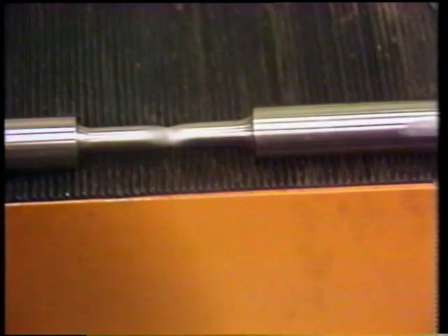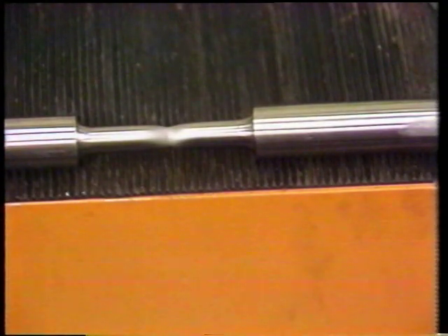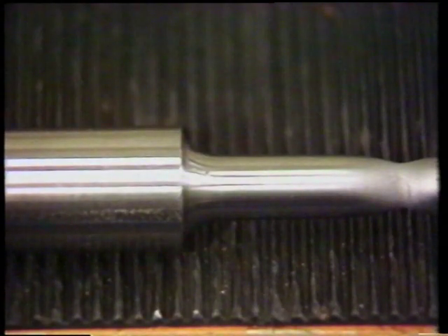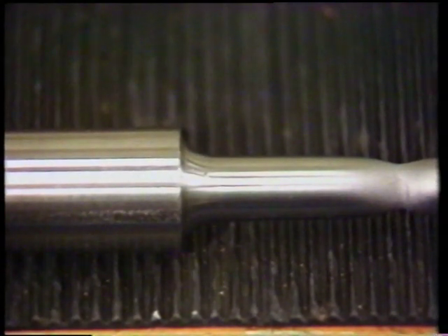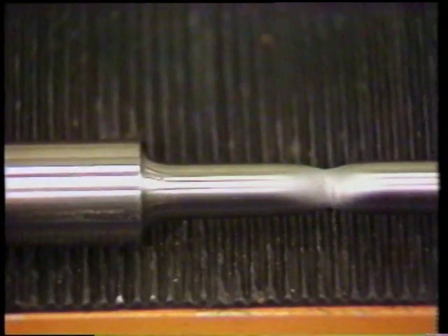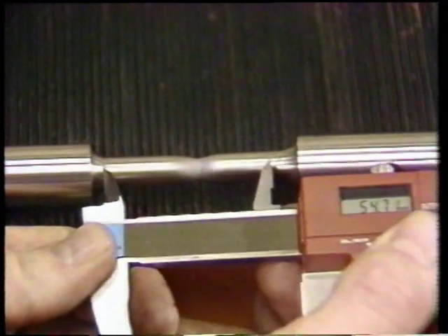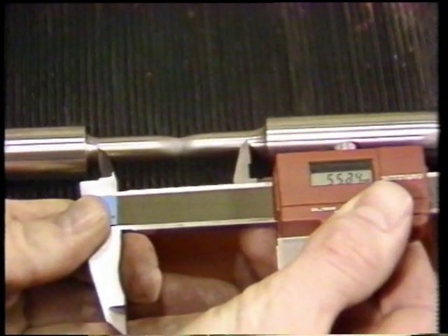A different property which tells us about the material's ductility is the elongation. And we get that by measuring the extension of the gauge length. Before we test, we put two centre pop marks on the specimen, on the gauge length, at 50 millimetres spacing. To measure the elongation, we very carefully replace the broken pieces and measure how far those pop marks have increased.